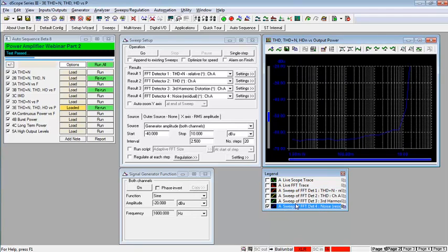If I now look at the noise measurement, this doesn't look like a contender either. This is showing me that the noise seems to be broadly constant at low amplitudes. And when you think about it, that's probably what you would expect. You would expect that the noise at the output terminals of your amplifier was independent of the signal amplitude, in most cases anyway. Now, one thing to notice here is that I've plotted noise on an absolute scale, so dBu. That's an absolute measurement unit, and that shows us, as we've said, that the noise measured in absolute terms is flat.